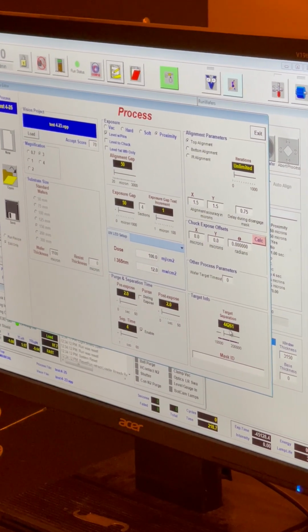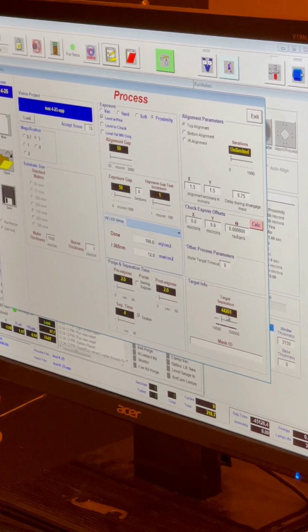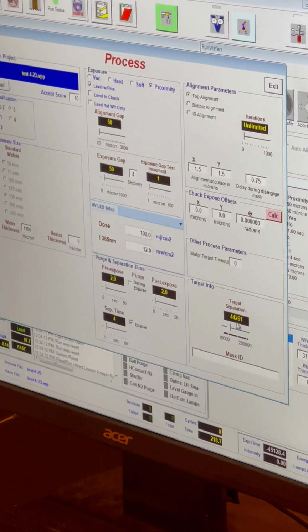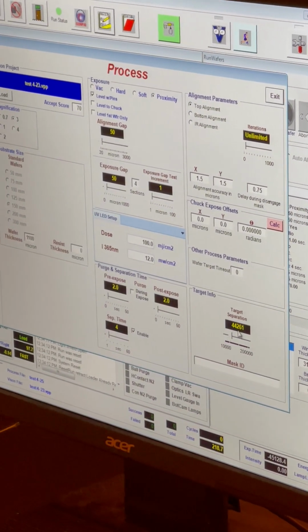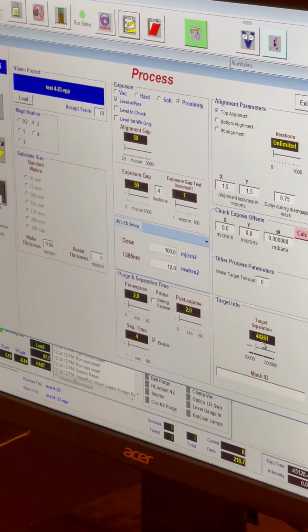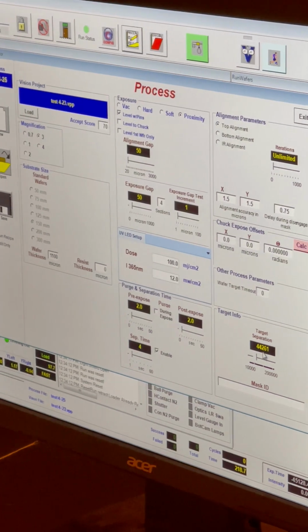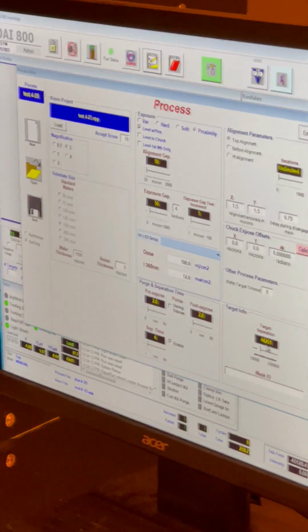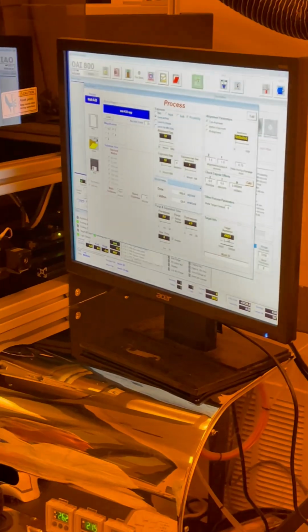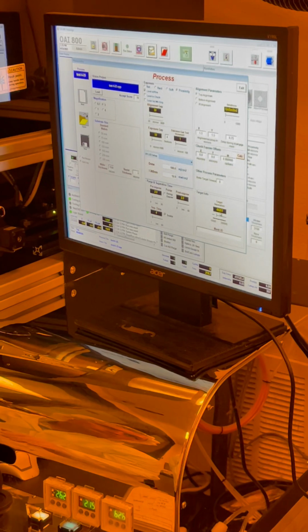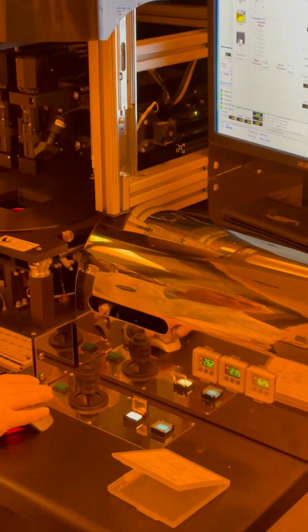And then you have to tell it on this tool what the separation distance is between the two mask alignment marks. You have to do that so that it knows the theta adjustment to make when it calculates a misalignment. The reason for that is the optics are controlled by a joystick and they're motorized, but for the x-axis there's no encoder, so it doesn't know how far apart these are. So that's the recipe.